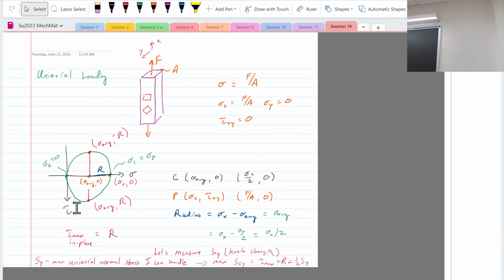Okay, so there are a couple ways to do it. Plotting it is the easiest, right? But if you look at what we'll put out there, to calculate the maximum shear stress, you can take the derivative of the shear stress transformation equation and set that equal to 0.